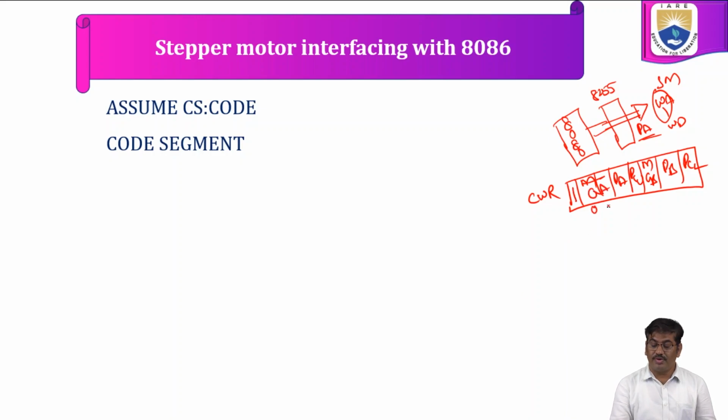So as the mode of operation is 00, that is mode 0, we will write the mode of group A as 00, and we are using port A, that is also in output mode. So the port A bit is equivalent to 0. Remaining ports are not required, so they will become don't cares. So from 80H to 8F we can give any value. By default we will take the values as 0.